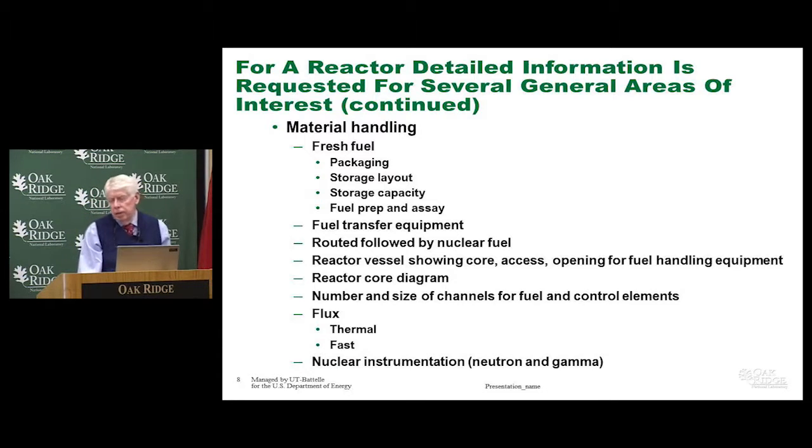What kind of fuel prep is done on the fuel once it comes into the facility? Are there any quality assurance aspects in which the fuel is examined? If so, what are they? Do you take an assay of the fuel to confirm that the enrichment, the isotopic composition, material composition of the fuel is as it was when it left the fabrication facility and was essentially contracted for? Or do you accept the results from the fuel fabricator? If you do that, where do you do it, and who does it?